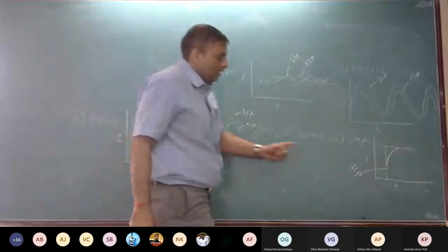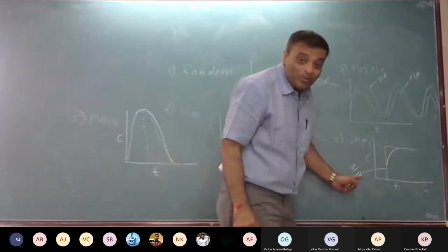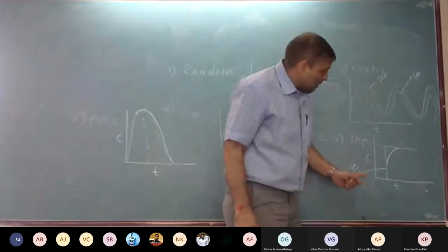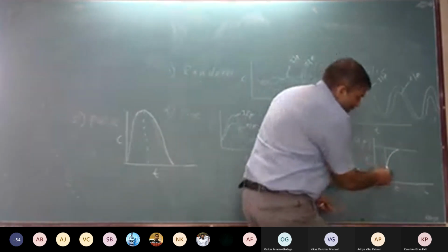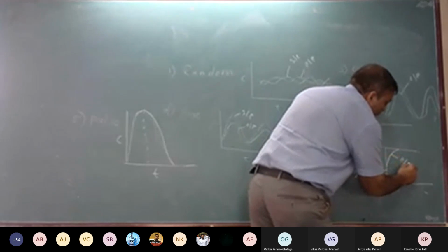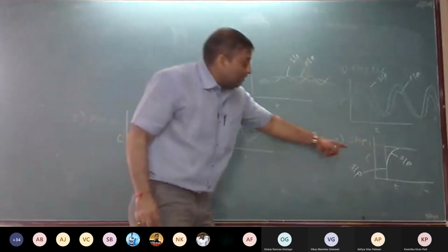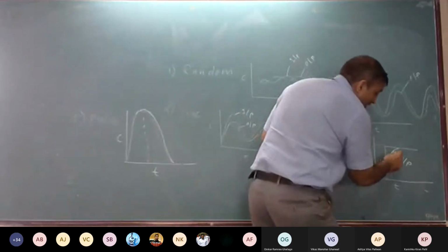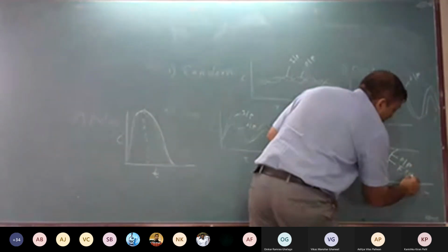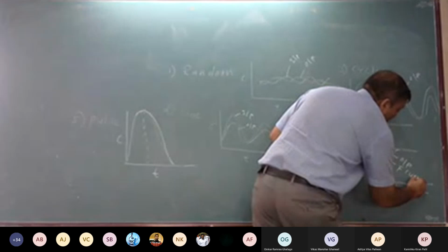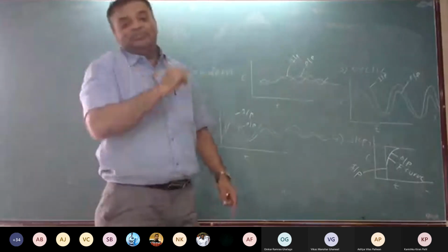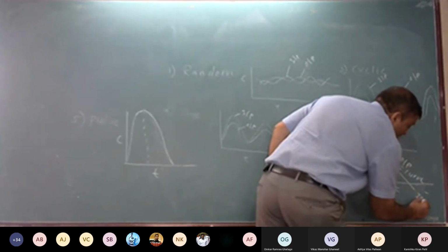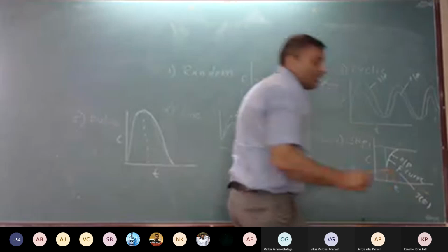Understand this, it is very important. Here the input is a step. What is the output? The output is this curve. And this curve, when step input is there, whatever curve we are getting, that curve is known as the F curve. When we are getting step input, this F curve is also known as the J theta curve.